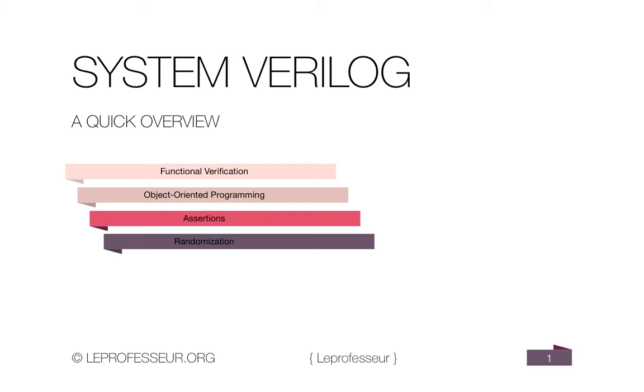It's very important. Think about that you're going to buy a cell phone and the cell phone IC breaks. You find bugs in that. Would you like to buy that? No, absolutely not. So what engineers do, they try their best to capture all bugs, but in theory it is very difficult, close to impossible, you may say. Think for a second, if you want to verify the whole address space of a 64-bit processor, think about 64 lines, and each line can have 1 or 0 value. So how many combinations would it be? 2 to the power 64, an enormous number. That many test cases you would need if you want to verify each combination. In reality, it is not possible.